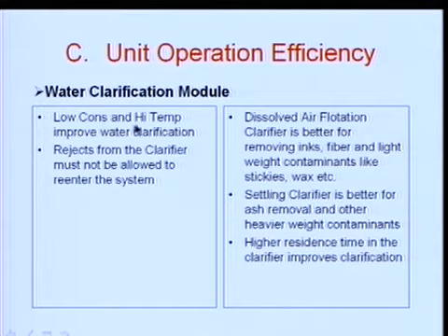Low consistency and high temperature improve water clarification. Low consistency depends on the kind of water clarifier you use. Generally, most people use dissolved air flotation clarifier, which is better for removing inks, fiber, lightweight contamination like stickies and waxes, and those are the contamination we are mostly concerned with. Anything that is heavy and solid or rigid is more easily removed during the thickening part of it, and all the water that's left afterwards contains most of these contaminants.